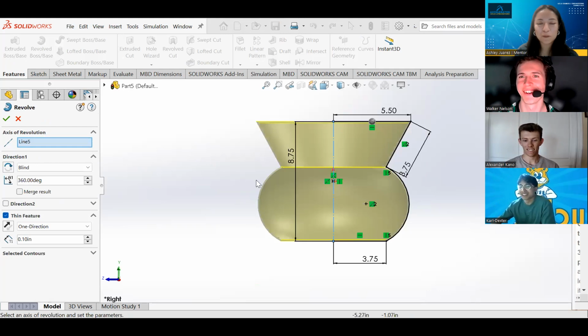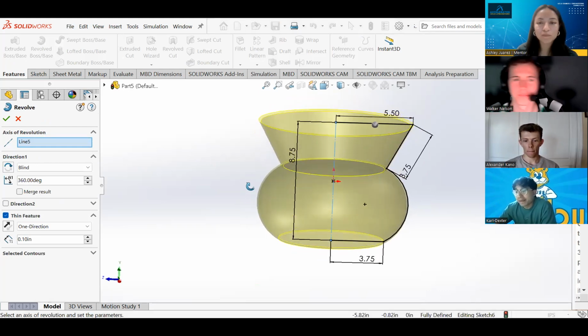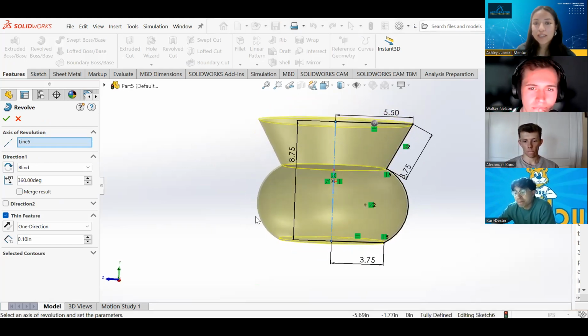But yes, remember Calc 2. It thought it had an open line. And remember, this is why I said all your lines need to be closed. Everything needs to be shaded in if you have the selected contours on. Because if you want to create a revolve boss or an extrude boss, whatever it is, Solidworks can't do that unless it knows it's a definitive thing.